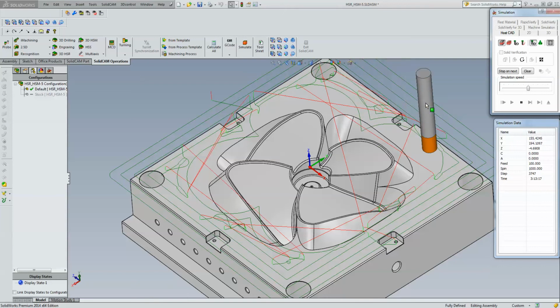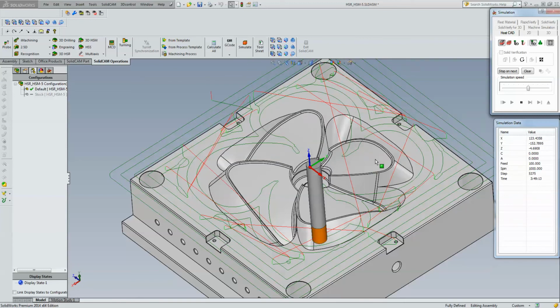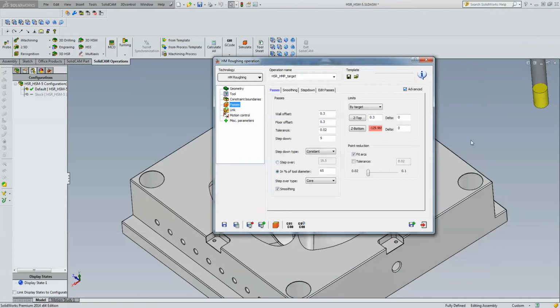Okay, this is not a pure core part. There's some parts that are actually pocketed in there also as well. So this is giving it a little bit of confusion. But however, it is doing the work, and it's doing it actually pretty well. But let's see a different option we can use instead. Let me actually stop this. And we're going to use the option of, instead of core, we're going to use the option of HSM.